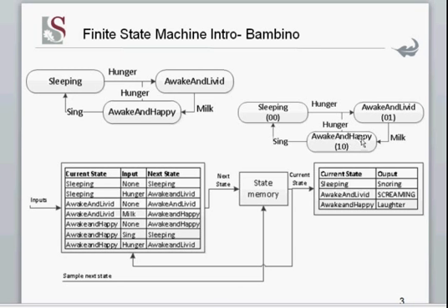Three states require 2 bits, so there's one state that we don't use, the state 1, 1. This is important, you'll see now, because that next state signal there is really going to be the number of lines that represent the number of bits that we have to use to save the state. Same here, present state or current state will also be 2 bits, which implies that we'll have to have 2 flip-flops to remember what state we're in. Remember, 1 flip-flop remembers 1 bit, and the next state logic will have 2 outputs, and then this output logic will have 2 inputs to determine what the output should be.